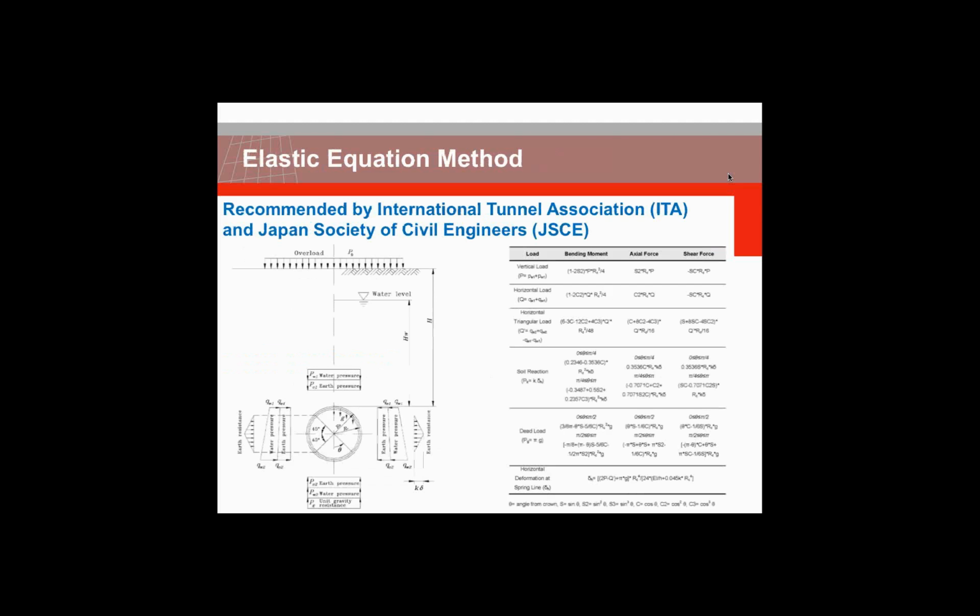Okay, the elastic equation method is recommended by the International Tunnel Association, ITA, and the Japan Society of Civil Engineers. As you can see in this figure on the left side, the distribution of the loads used in this method is as such, and due to such distribution of the load, in the table on the right-hand side, you can find the equations for calculation of member forces.